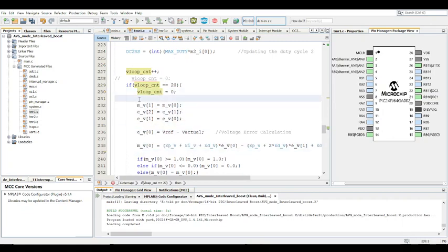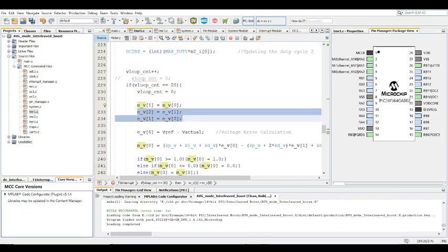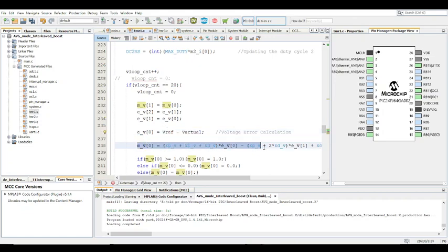So this is the PID. This is PID control, velocity mode PID control specifically. So these are the steps. This is the first step, the PID control step, and then the error as well. So basically this is the previous PID control step being equated to the current PID control step. Obviously when it does this for the first time, this particular value will be 0.0 as initialized, and this is the previous error equated to the current error. Okay, and then now you update the current error value, and then you execute the PID control loop.